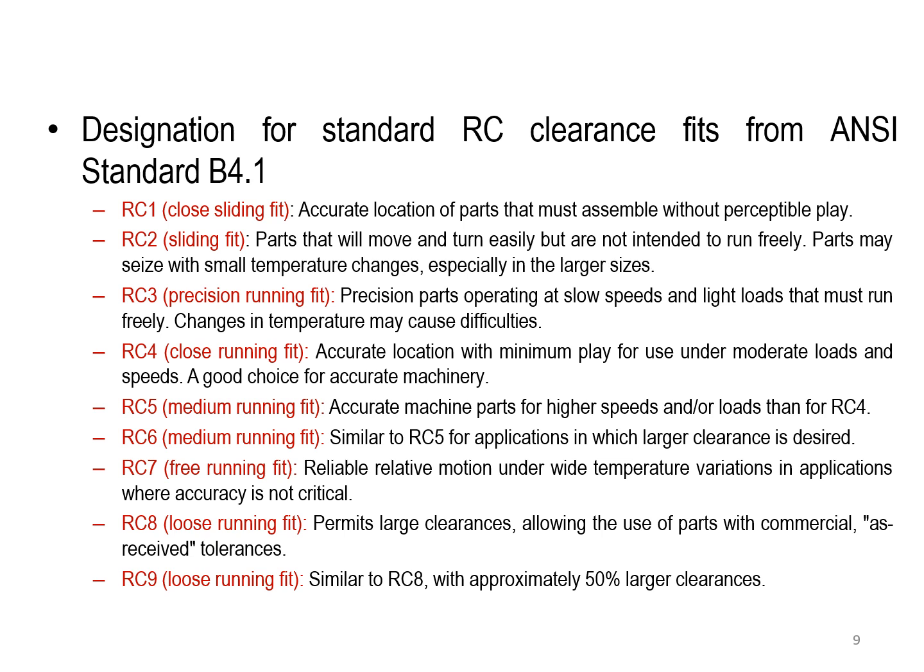And the RC8 is the loose running fit, which permits large clearance, allowing the use of parts with commercial as-received tolerances. And the RC9 is a loose running fit, similar to the RC8, with approximately 50% larger clearance.